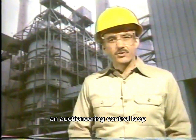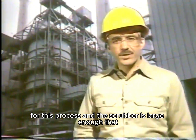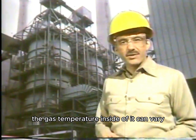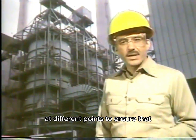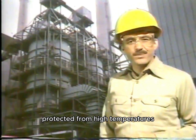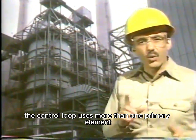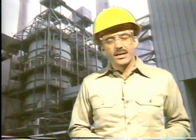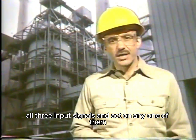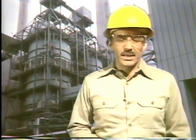An auctioneering control loop is an appropriate control loop for this process. Now, the scrubber is large enough that the gas temperature inside of it can vary at different points. To ensure that the scrubber is adequately protected from high temperatures, the control loop uses more than one primary element. In addition, the controller is designed to receive all three input signals and act on any one of them.